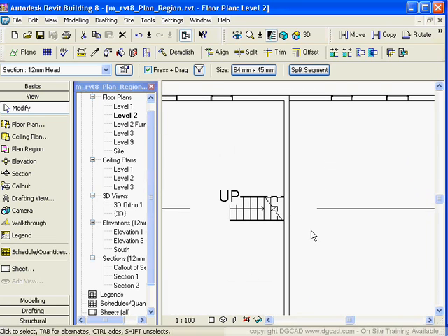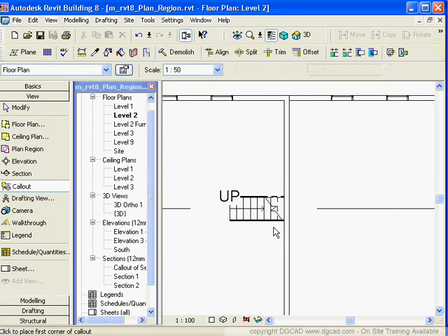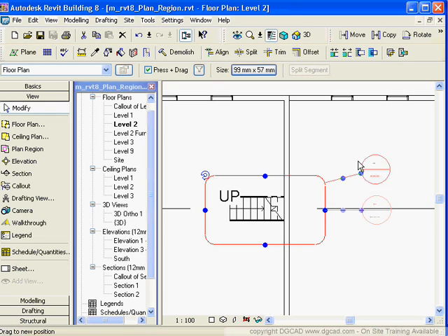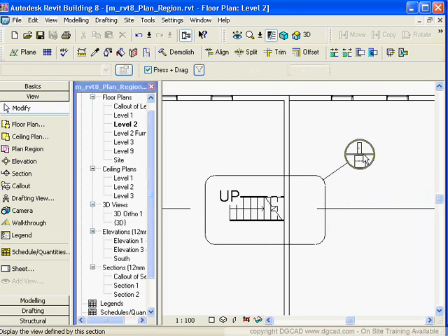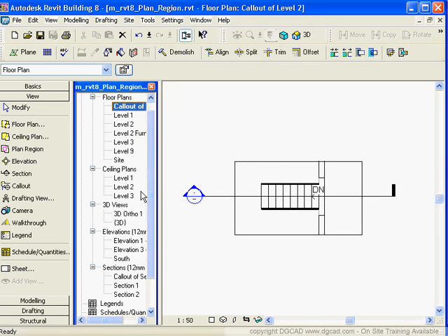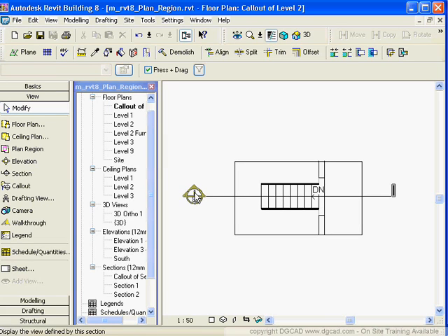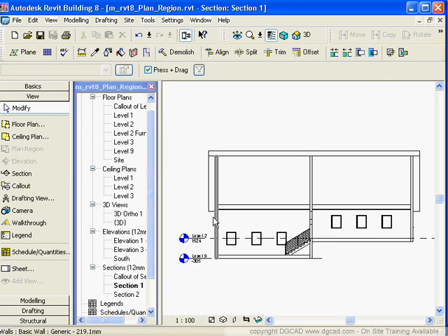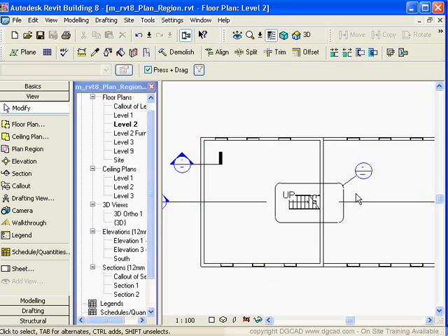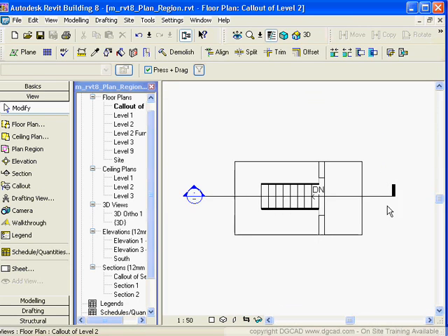Now if we do a plan call out, it's a bit different. If we go up into here, and this isn't a really detailed drawing, but I can go in and do a call out here. This call out will be different from the last one because it's a plan call out, not a sectional call out. If I double click on it here, it's going to create it. You'll notice it got placed up inside of here with floor plans. Then I can click on this, and it's also telling me there's a section that's tied in, which is very nice.